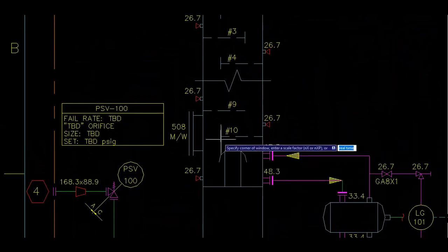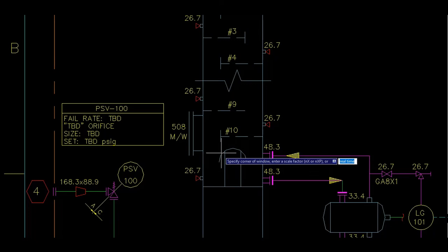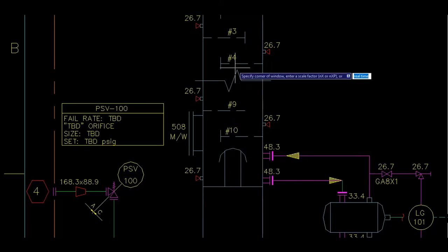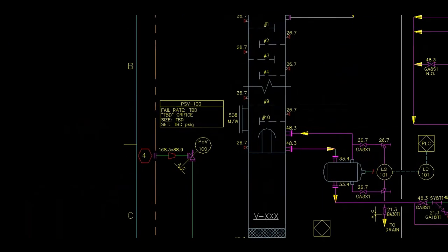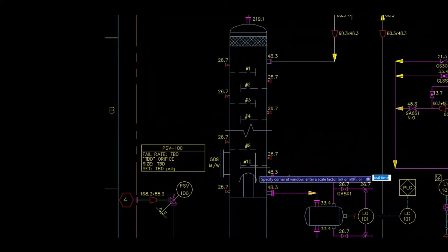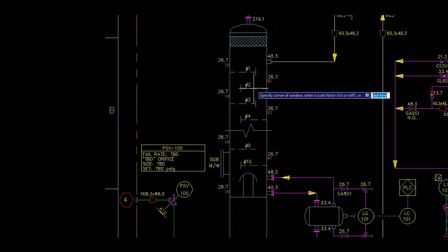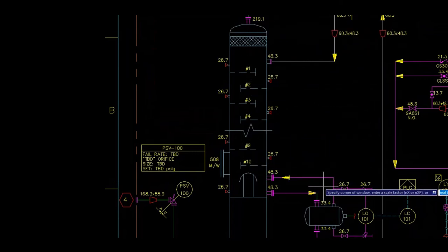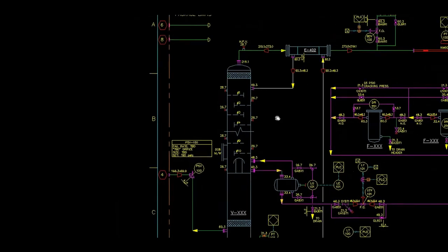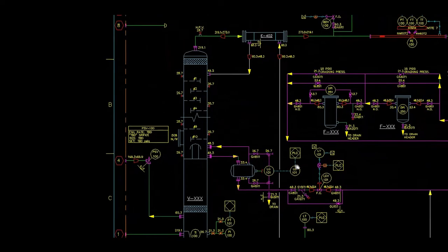The arrangement given here is a chimney with an inverted cap. This is to prevent the gas shooting upward to the bubble cap trays and possibly damaging the plates. There is a level of glycol here, so gas enters that volume and rises up evenly. The velocity of the gas is reduced by this arrangement. Gas will evenly pass through the bubble cap trays against the downcoming lean glycol. During this process, water in the gas will get absorbed into the glycol phase.